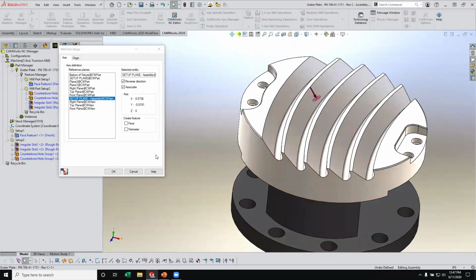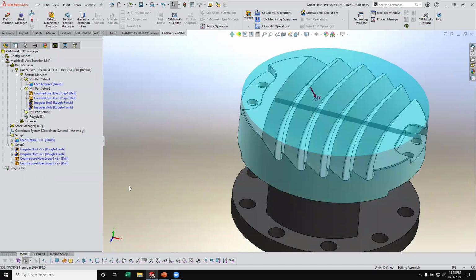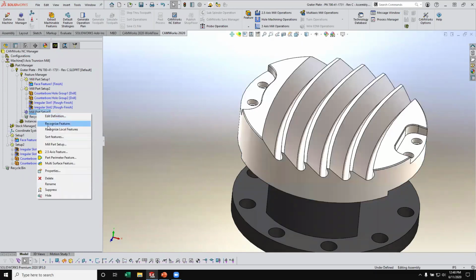When I'm 3-axis roughing this under a preposition state, even though it's 5-axis preposition, it's going to clamp the rotary axis so it's more rigid for roughing versus doing it all simultaneous. If it's all simultaneous, the rotary axes are unclamped, so it's not as rigid, so you can't rough as aggressively. But I want to be more aggressive and more efficient, so I want to rough it as 3-axis, tilted at an angle, so it's prepositioned with the rotary axis clamped. Okay, and because it's prepositioned, it'll be clamped. So I did that setup.